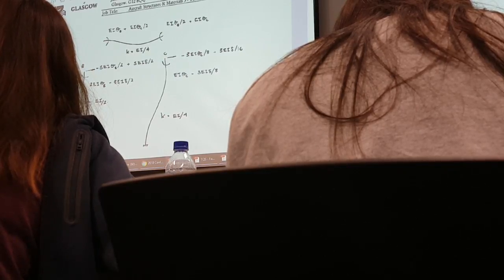So this has to be node 1 and node 2. And for member BC, this is node 1 and node 2. And for CD, this is node 1 and this is node 2. So after that, you go back to apply all your M1, M2, PY1 and PY2, and you should get all these equations. For example, for node B, you need to apply the equation M2. When you use equation M2, you will be able to get this particular expression for your moment about B. Remember BA.